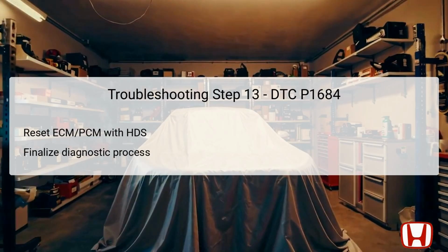By employing HDS, which allows for precise and reliable communication with the vehicle's systems, the technician can ensure that all error codes related to previous issues are cleared. This action signifies the completion of the repair or cleaning protocols and prepares the vehicle for final evaluation.